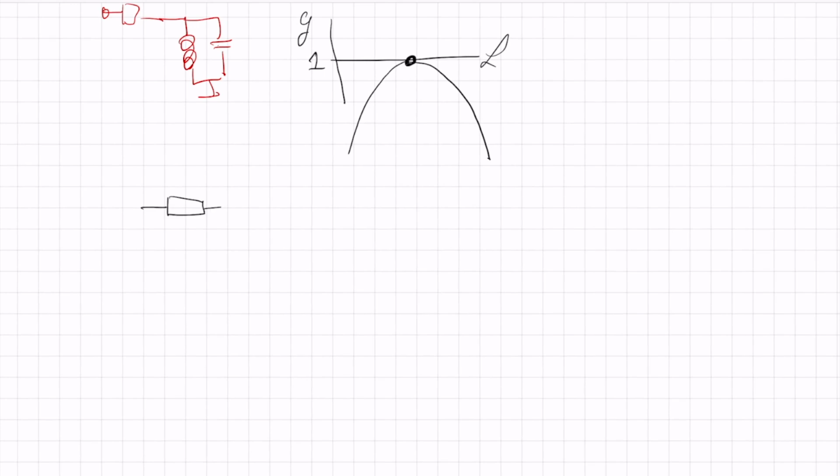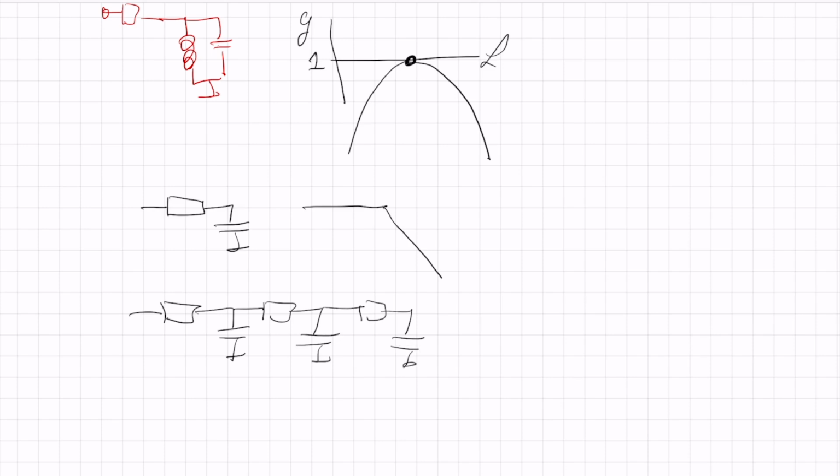So a very simple low pass filter is an RC filter that has this famous first order low pass characteristic. And of course, if I want higher order, because normally you like higher order because you want to remove the interferers and also you want to prevent aliasing in your ADC. So then you could say, let's put a big cascade of those first order filters. For example, third order is quite popular.